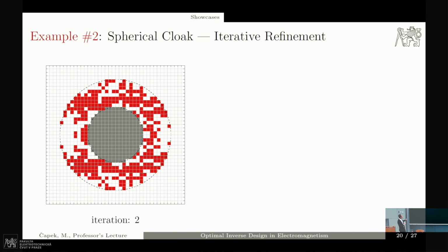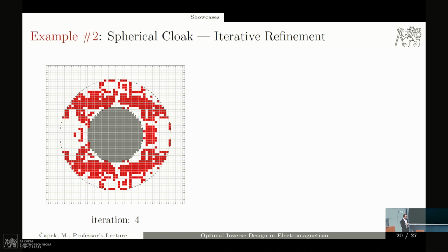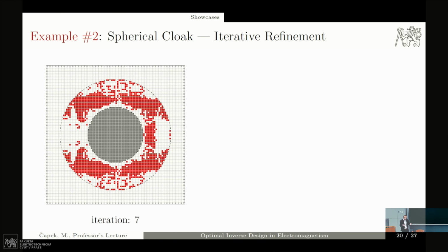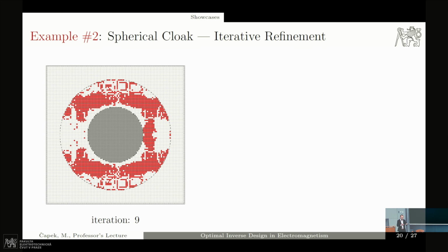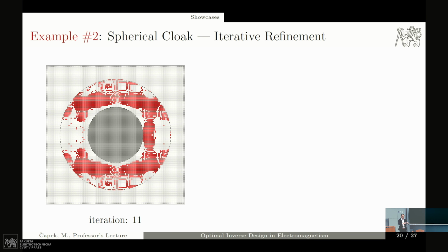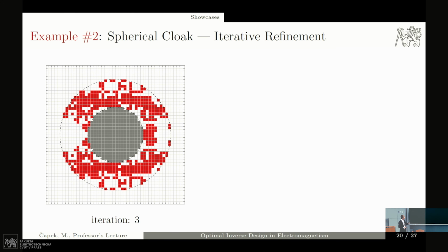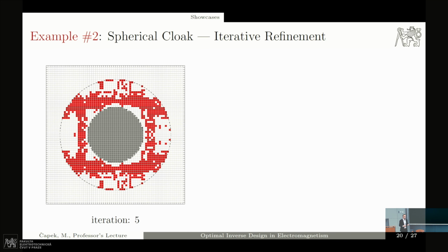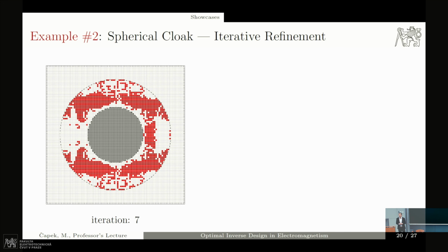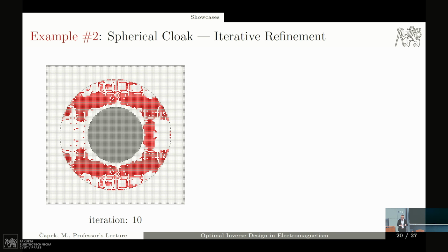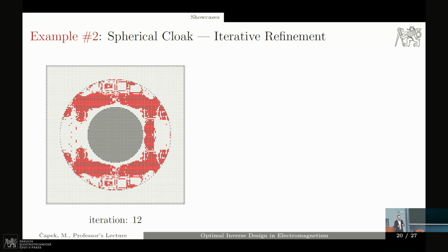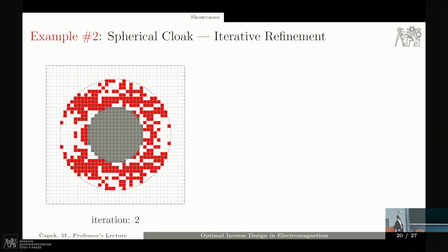And with that, I would like also to demonstrate that we have some iterative scheme with our algorithm, which starts with a rather poor mesh, finds optimal solution, translates it to a finer mesh, and again. So at the end of the day, we can deal with 10,000s of optimization unknowns in a reasonable time. And again, it's thanks to the local gradient-based algorithm, which is on the very bottom layer of this.